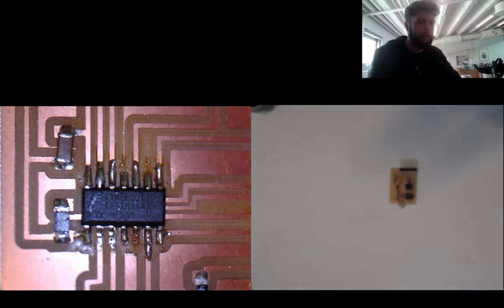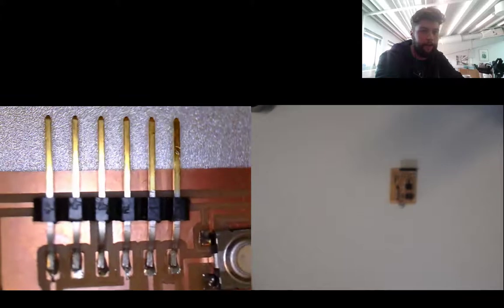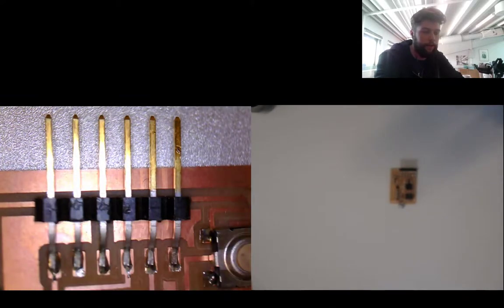If we take a look at an even tinier board, here's a different board, and this one specifically has a 6-pin header, and this pin header can be used to program the board through a UPDI or an FTDI cable. I strongly recommend having this cable because it makes for much easier programming afterwards, but it also provides power, and you can use it to communicate with the board on the go. You can communicate with it while it's working. You can't do that through the ISP specifically.